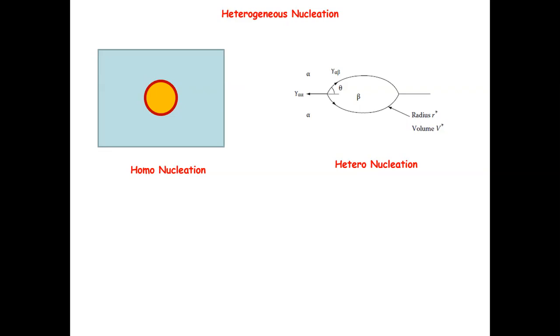So if you form a nucleus there, the chances to use the extra room to accommodate some of the volume change will be much higher than near a dislocation. For a dislocation, you can also do this, but it wouldn't have a lot of freedom for you to adapt the volume, or use that defect to reduce the contribution of the volume increase to the total energy of the system. I think that provides a rationale why grain boundary is more favorable for heterogeneous nucleation.